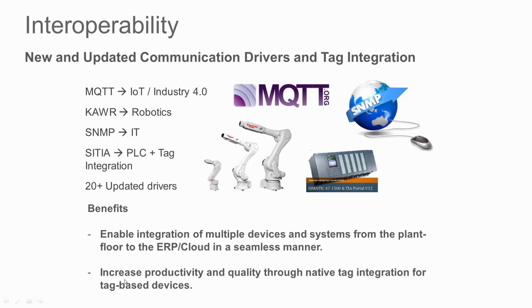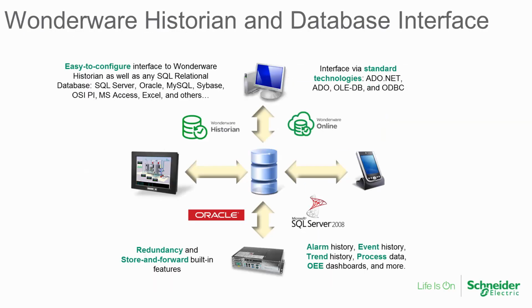system, a cloud. And in addition to how I mentioned that you might have like a 2-column spreadsheet, well, some of the devices that we have, we use this thing called tag integration, where we can actually import the tags from the output of the control software and be able to work with those tags. For example, if you export 1,000 tags from the control software and you only use 5 of those, it only uses 5 of those in InTouch Machine Edition. So it's real handy, real easy.